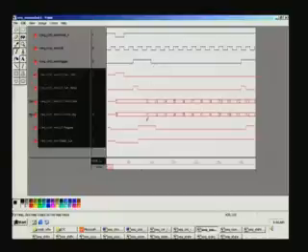We preserve the current value of the trigger and then use it in the next clock cycle. Is that clear? That is how you sense the rising edge. And if you see the run delay here, for the time being it is counting 1, 2, 3, 4, 5, 6 and so on, and not much information here, and we will come back to it.